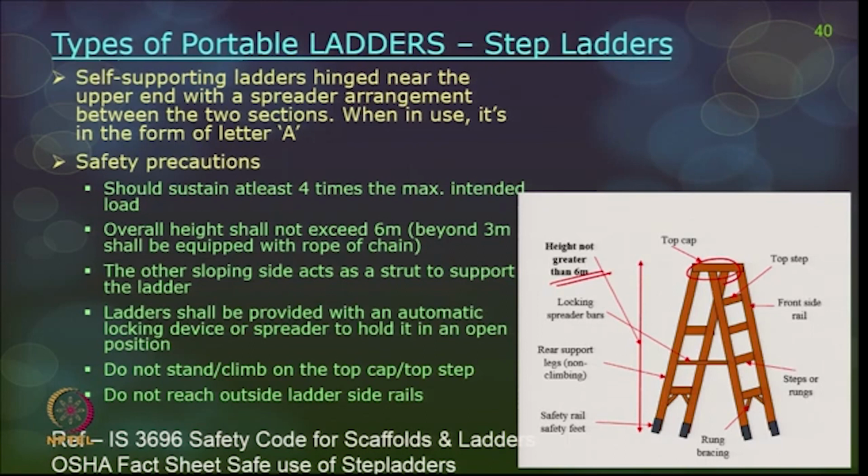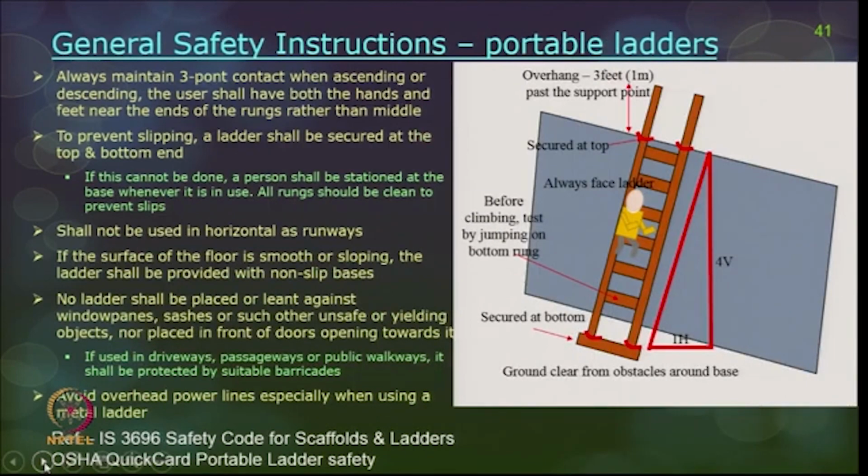Do not climb or stand or try to do anything with the top cap or the top step, and do not reach outside your ladder side rails. Again, it is primarily the awkward posture. Do not try to extend or go above the side rails to reach out for something. That is not advisable and you may have a fall hazard.